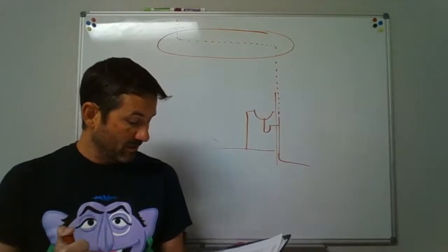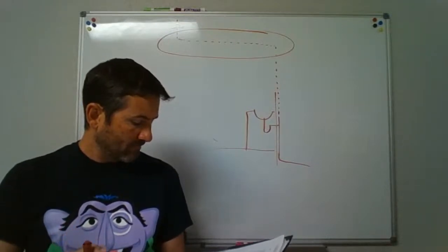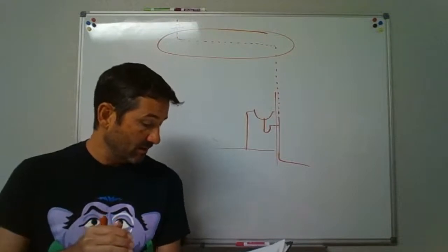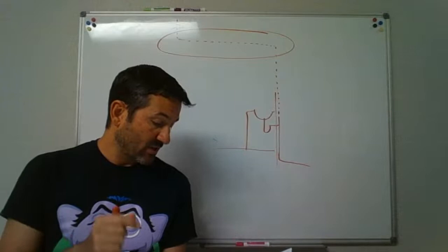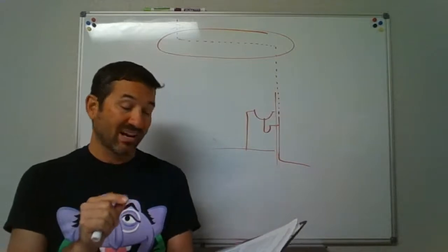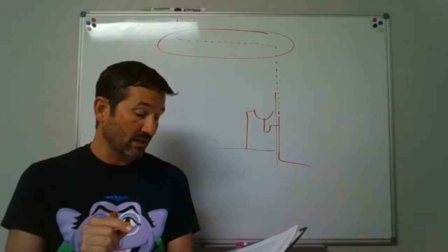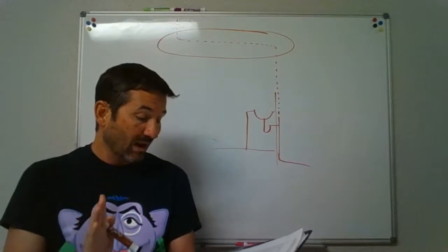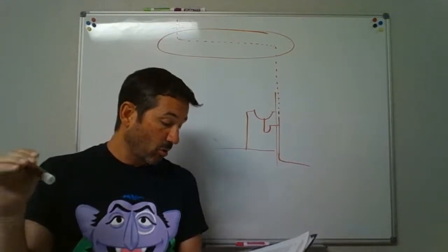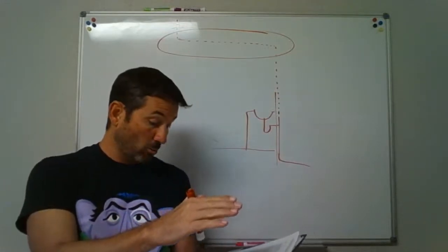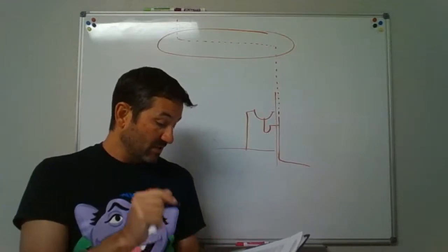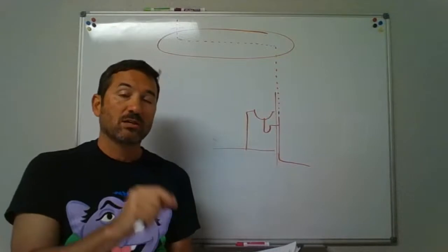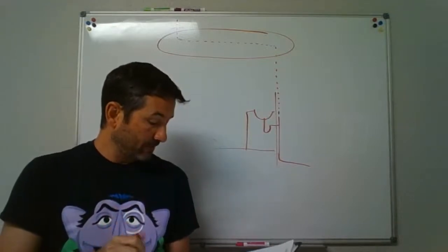I'll continue on. They do put a couple of exceptions in there as far as vents for interceptors located outdoors. And when vents for interceptors and isolated floor drains are not located near an adjacent wall, the vent can rise 6 inches vertically, turn horizontally, and continue to the nearest wall for cleaning purposes. A clean out the same size as the vent shall be installed. So you put a clean out on that vent there.